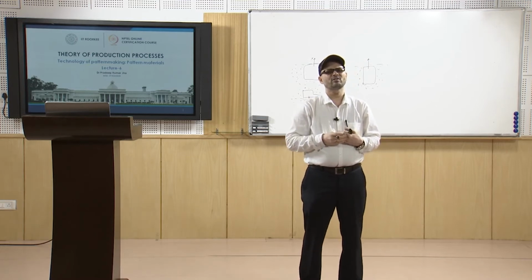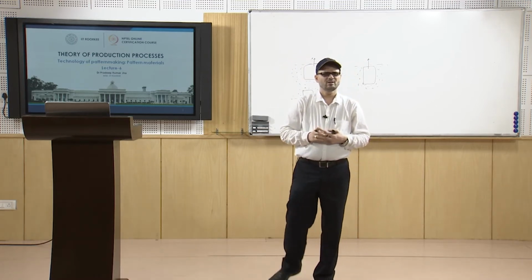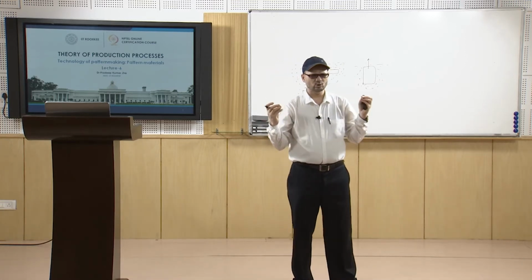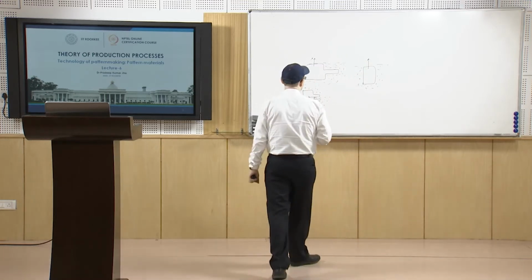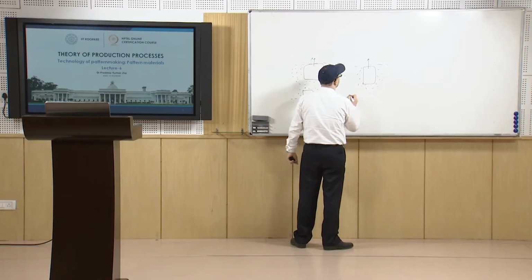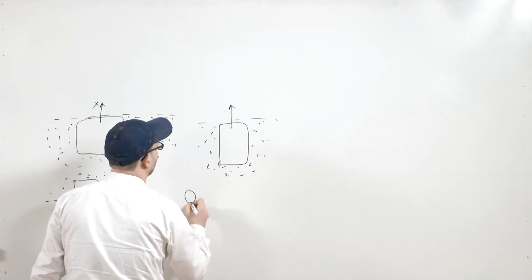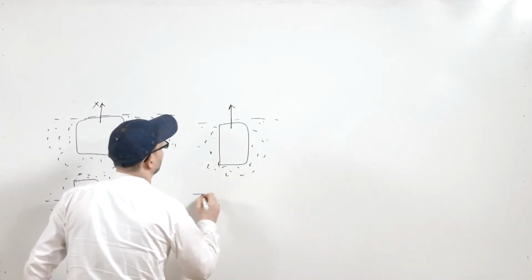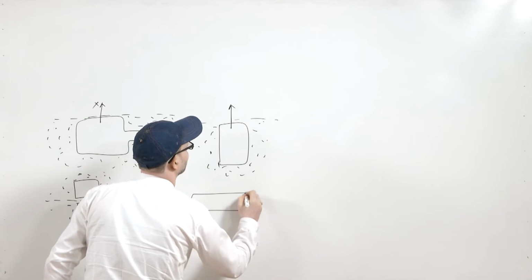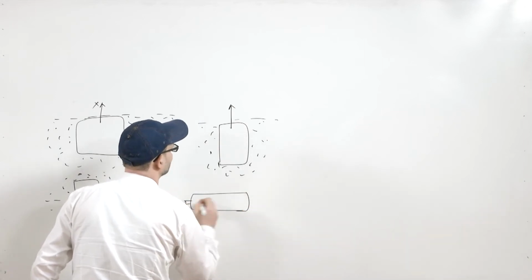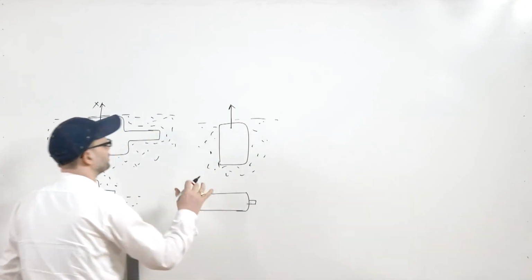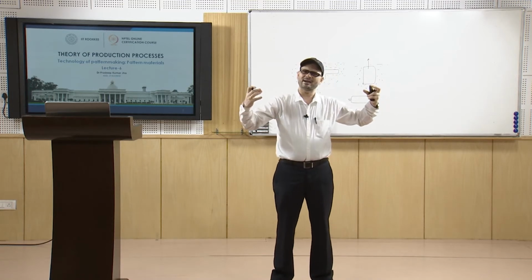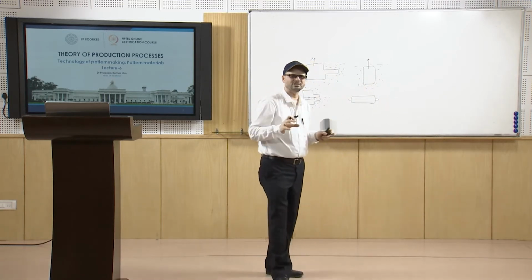Construction details like provision of loose pieces, core prints. Now, that is also to be seen, because many a times the core prints are those places on the pattern. So, if you are making the pattern, suppose you have a core. Let us know what that core is. Suppose you are placing a core. This core has to fit, so it basically has to have the support. That support is provided by provision in the pattern itself.